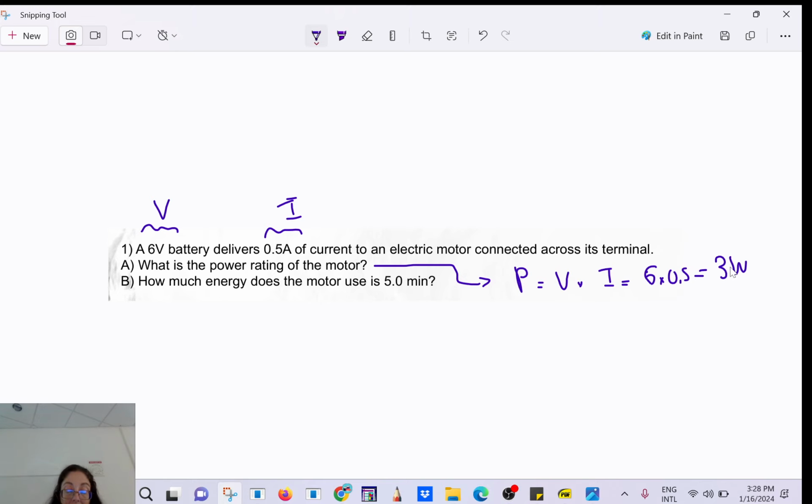So I look at my laptop. I bought it at Costco, by the way. They have very good deals sometimes. And my laptop, if you look underneath, it says 20 volt DC. So it means that the AC will turn into DC because a laptop does not like AC, it likes DC. And it says 3.25 amps. So when you buy another charger, if you lose it, you want to make sure that you have the right wattage. So you want to make sure you know how to find the wattage of your laptop.